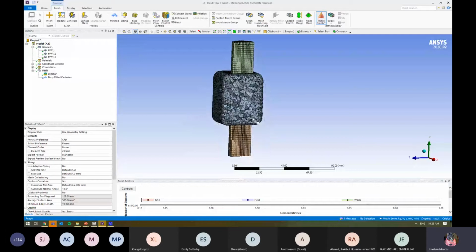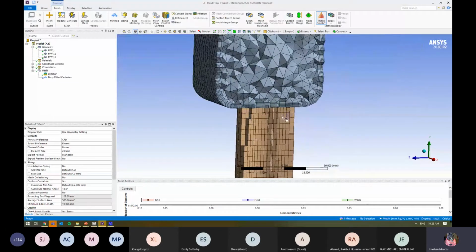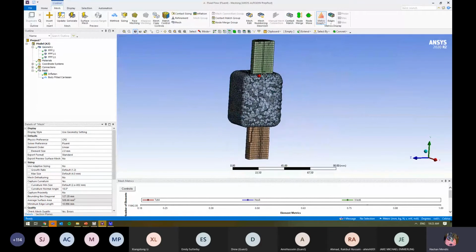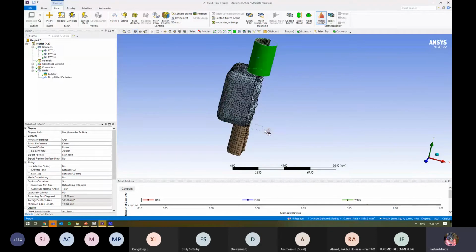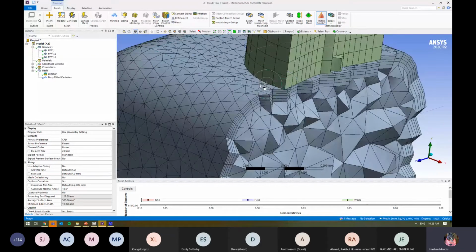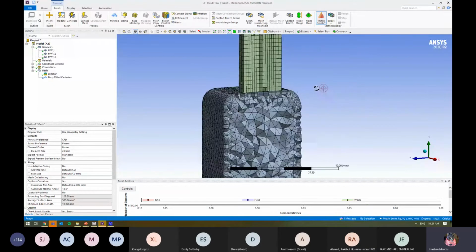We'll have a couple more elements across here, where we previously didn't have that. So there are benefits where you've got 2. What will happen though is that you've got some interfaces across there, and if the mesh is too coarse, or there's a large mismatch, we can have some interpolation problems through there as well. We can have some reductions in our accuracy.